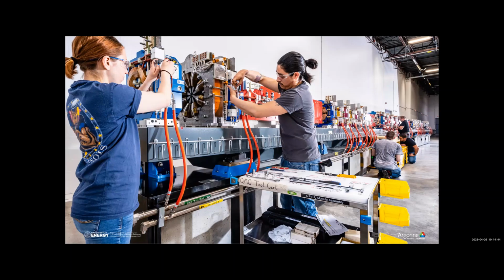And this is the machine that will give us and our user community a brightness increase of a factor of 500. It's quite a lot of work in terms of magnet technology, precision, alignment. The engineering is quite formidable. Each of these magnets is installed on this bench with a precision of about 10 microns. That's the thickness of a thin human hair, to give you an idea of the kind of precision we need for these machines.